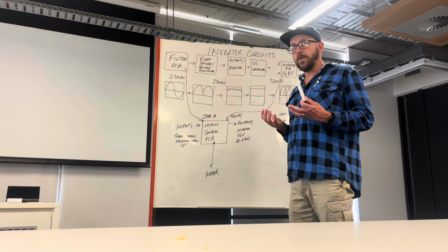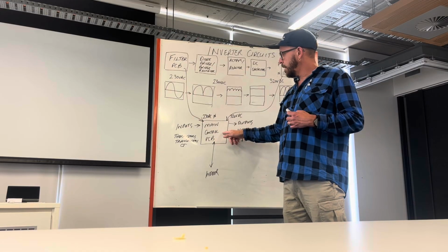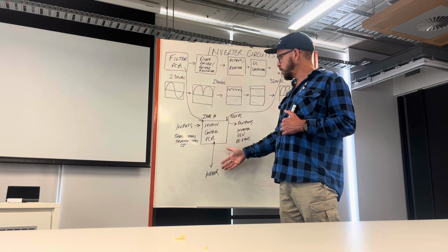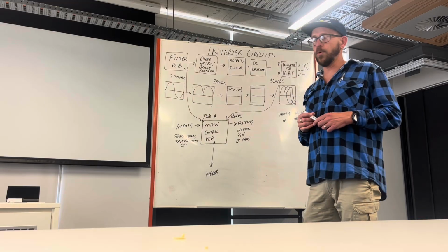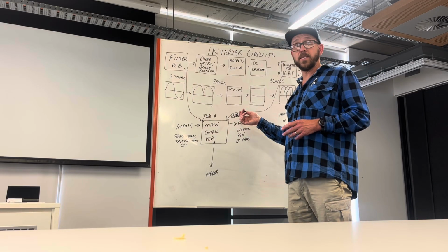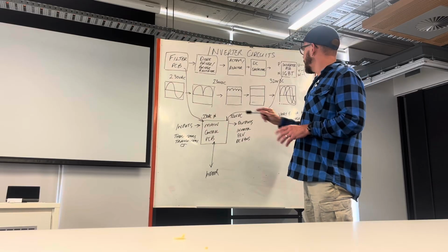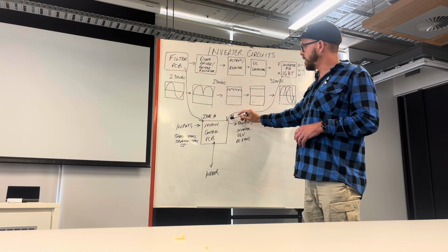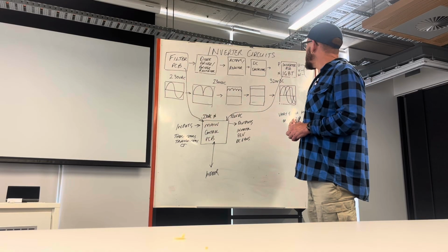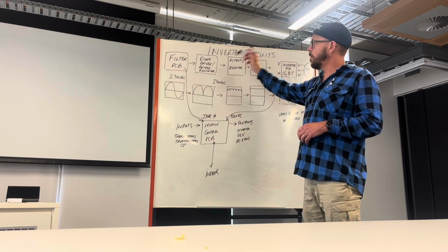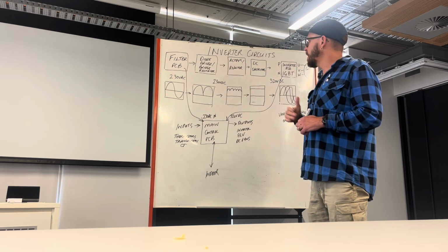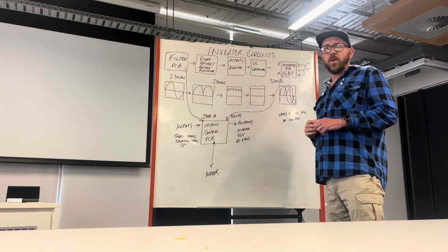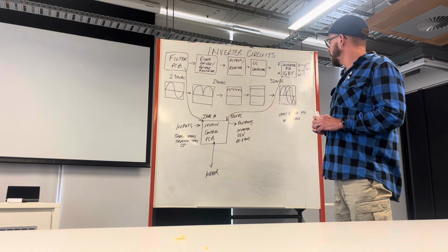So if I've got a comms error, a communication error on these sort of systems between indoor and outdoor, often people start with the main board. But if this main board doesn't have 320 volts DC, then it can't communicate. And that could mean I've got a problem up here through any of this DC circuitry that will hold out the DC voltage getting to my main board. So I could have a problem on my inverter, on my diode bridge, somewhere along there. We can go into how we test those components later, but this is just an overview of the different equipment that we have in the inverter.